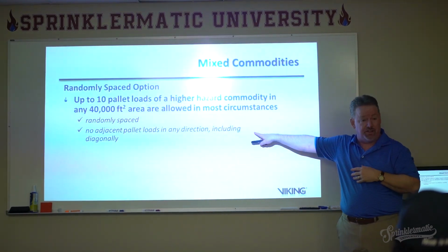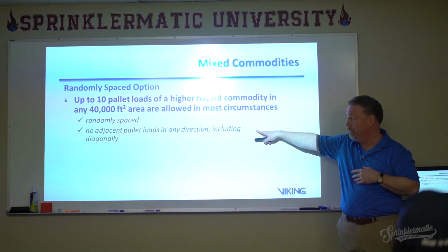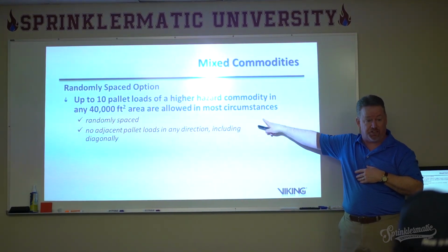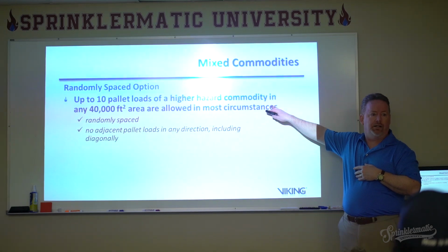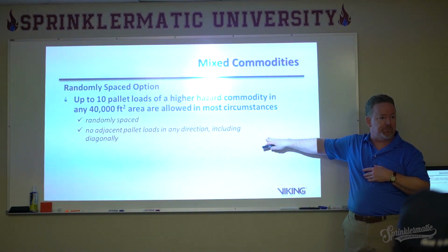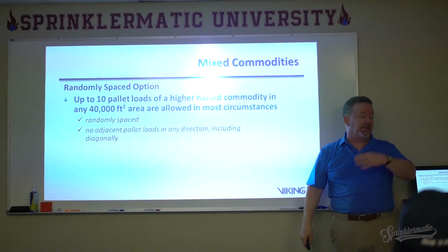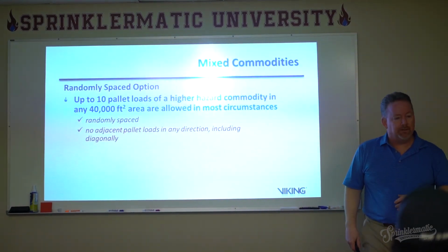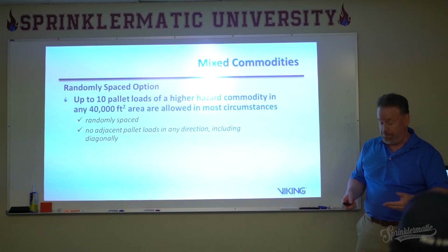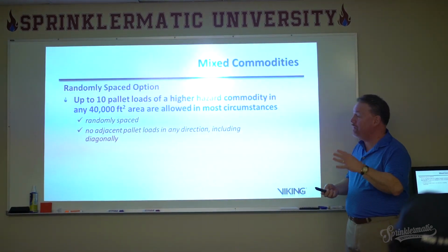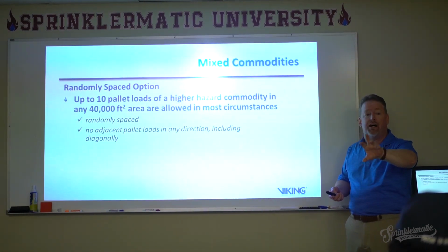It's never segregated, or you obey these particular Class A rules and segregate them to one section. So clearly it's going to be advantageous for them to do that, which is why you see a lot of people just go, yeah, just treat it as Group A plastic. Go ahead. It allows the most flexibility.